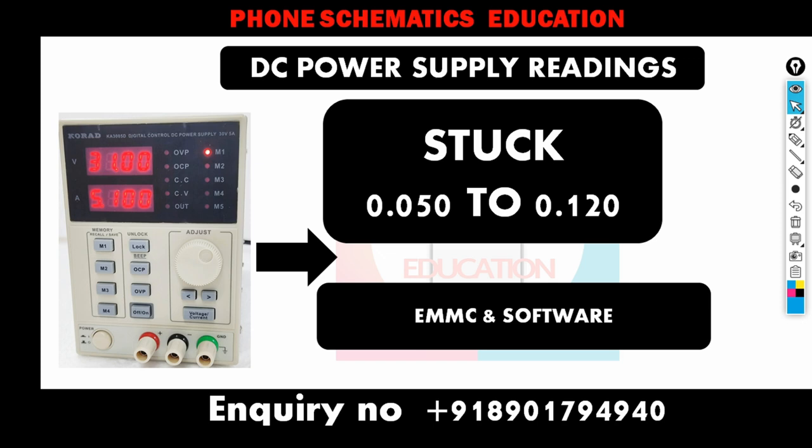Mostly in MMC. Also the software, your firmware. When the software is corrupt or the MMC health is bad, or the MMC voltage requirements and other requirements are not completed, your phone behaves like this, because your power IC boots, your CPU responds. But when it goes up to the MMC, the CPU does not find the MMC, the reading gets stuck, or maybe it is a software complication.